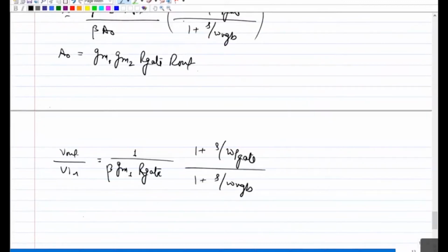So what does it mean? What is happening to the DC PSRR? How much suppression are you getting here? The impedance, the DC impedance, was getting suppressed by your loop gain.